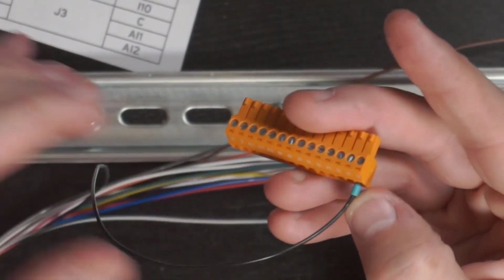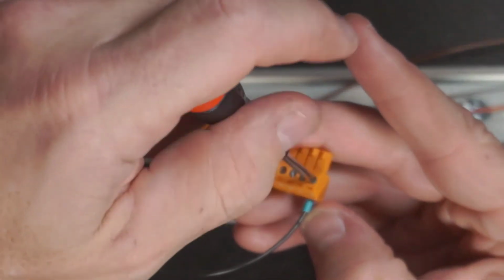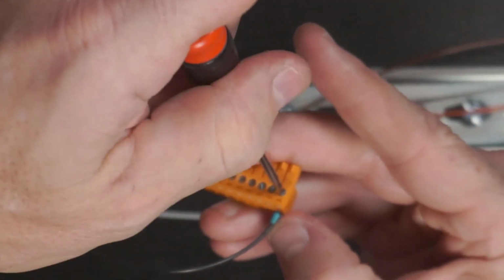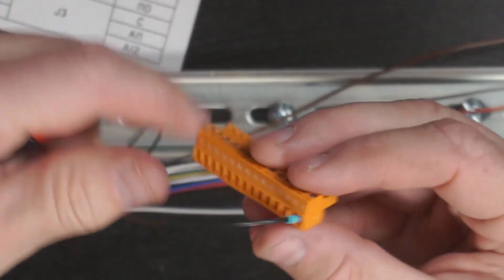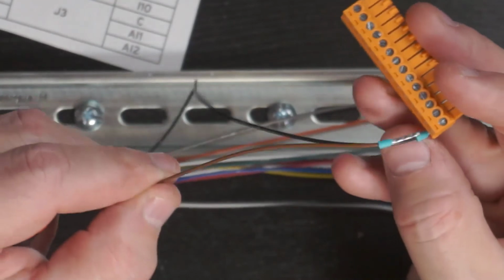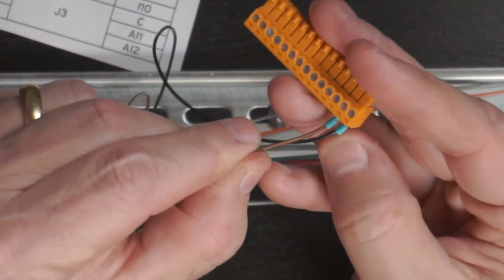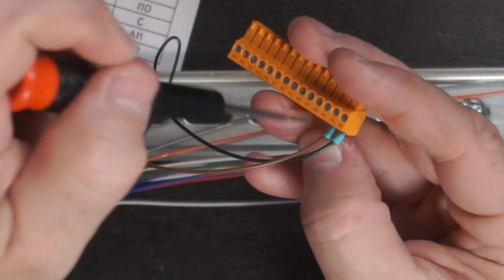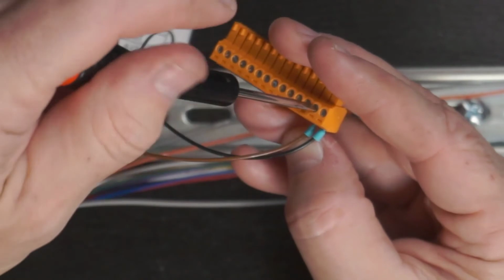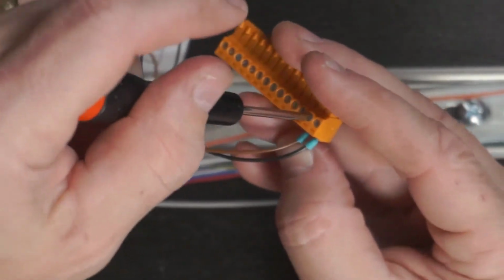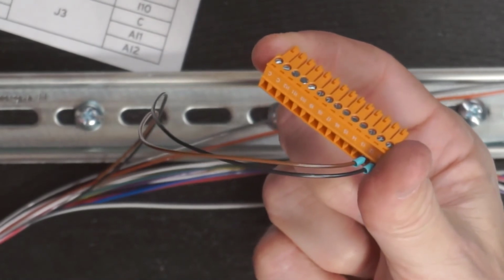We'll go ahead and get these first two wires landed live here, and then we'll go ahead and do the rest of them offline. Okay, so the ferrules are really nice. They make it easy to get the wires in the right location smoothly. They also prevent any loose strands of copper from getting where they don't belong. So I've got the first two wires landed, and I'll finish the rest of them offline.